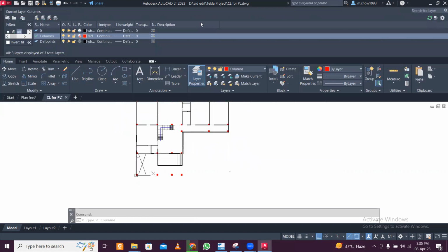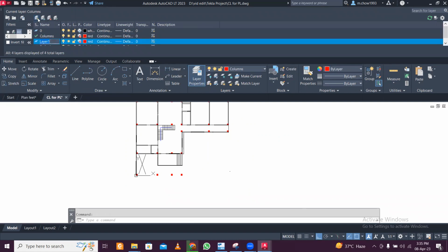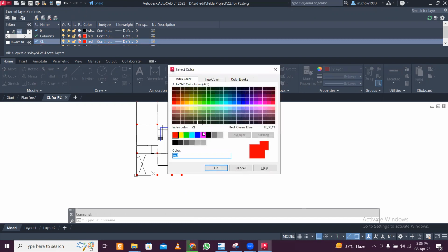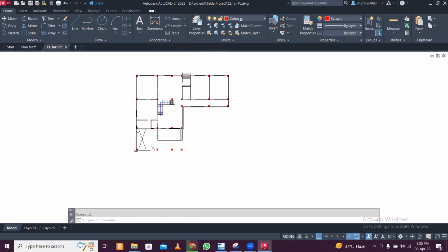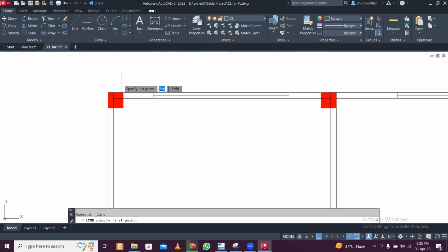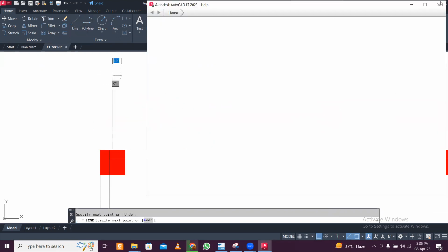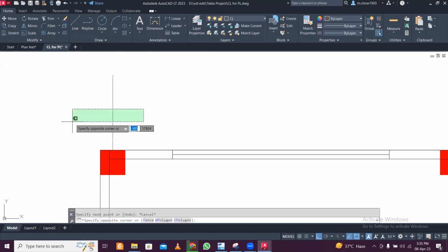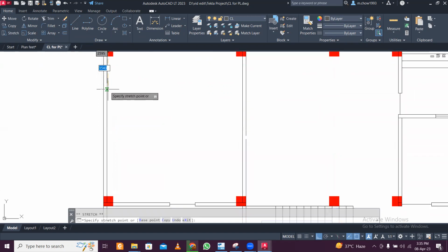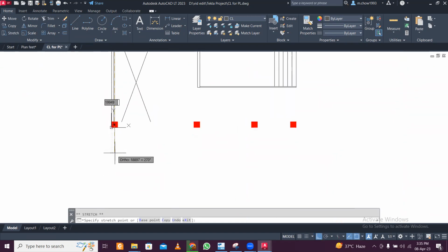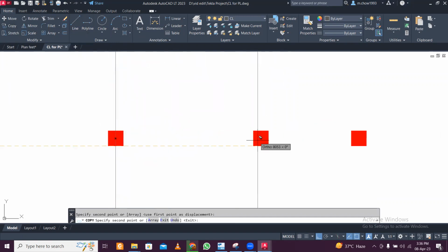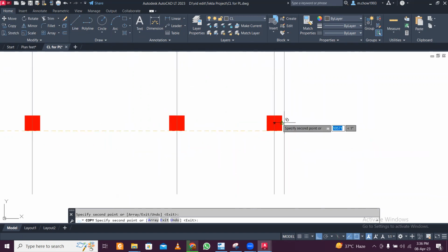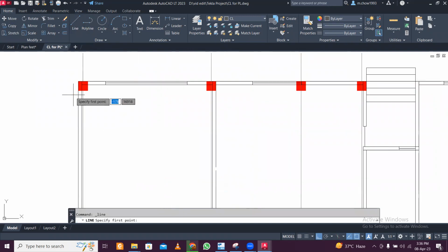So I'm going to create a new layer here, and this will be called our center line, CL. I'm going to take this layer as the 252 color, and click it again so it closes. Then I'm going to take this CL1 and draw a line at the center, escape, and then click it. Right? This first center line is created, the longitudinal center line, and then we paste it like this. Okay, another center line, let's create.